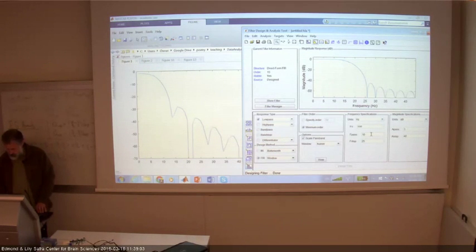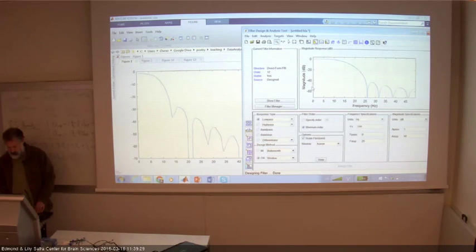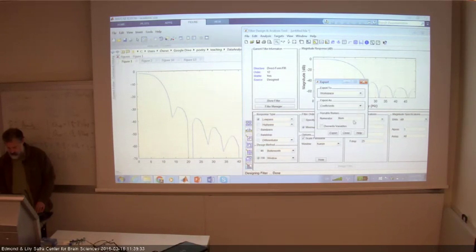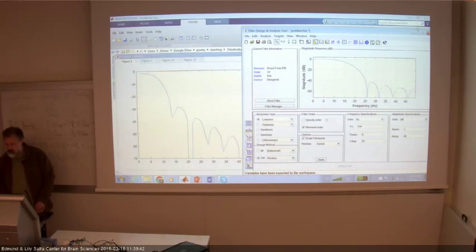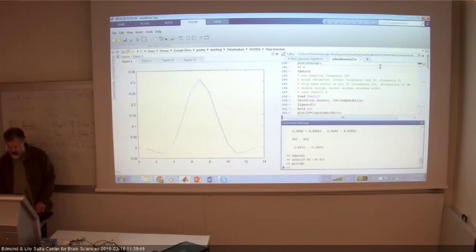So I want to get the low pass a bit more low passy, so I'll set a lower frequency here. I redesign. That's maybe a bit better. If we want, we can work a little bit more on it, but let's say that this works. So I decided this is what I want, so I now export. Again, I like to call these things B, for completely irrelevant reasons. So I have now this B. That's my filter.